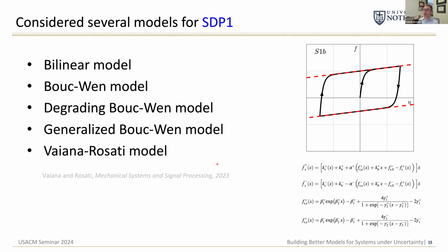Because in one case, I have a very true high fidelity model of a ship based on scantlings and drawings of an actual vessel. But I can also break that down into essentially a floating free beam. In some work I've done on that, you can show that you get similar modal properties, where the mode shape of the beam approximates the mode shape of the ship. The frequencies are similar, but clearly there's a lot of details that you're missing. However, that's an incredibly inexpensive way to approximate the behavior of that larger ship model.